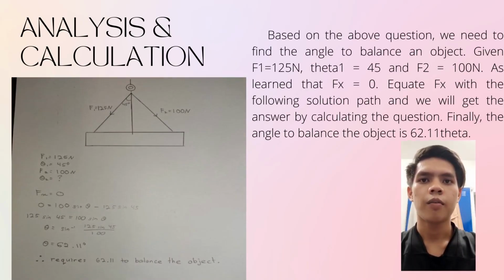Analysis and calculation. Based on the above question, we need to find the angle to balance an object. Given F1 equals 125 Newton and theta 1 equals 45, and F2 equals 100 Newton. Assume that Fx equals 0. Equate Fx with the following solution path and we will get the answer by calculating the question. Finally, the angle to balance the object is 62.11 degrees.